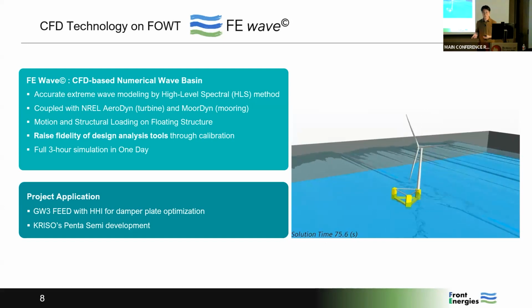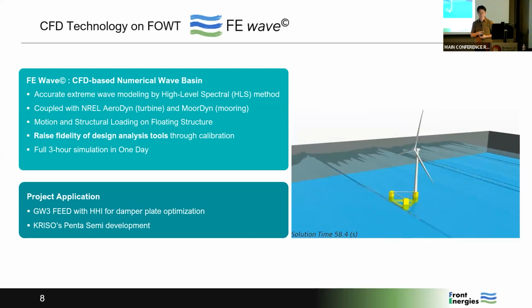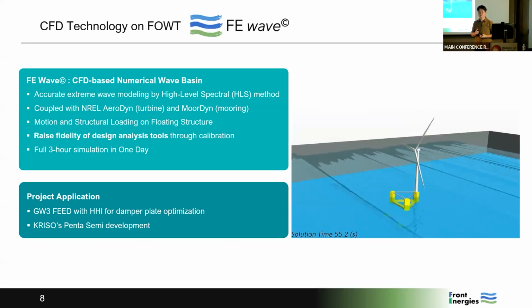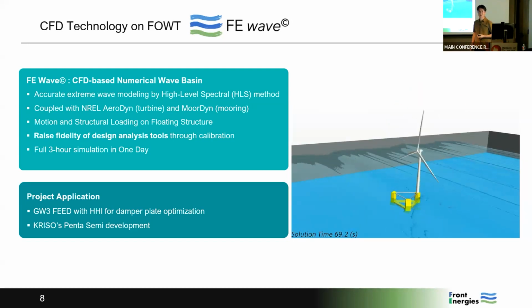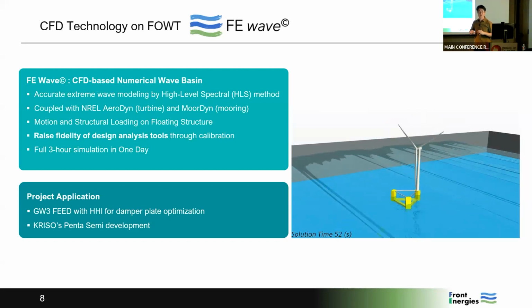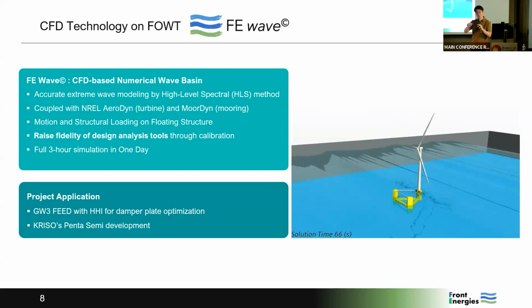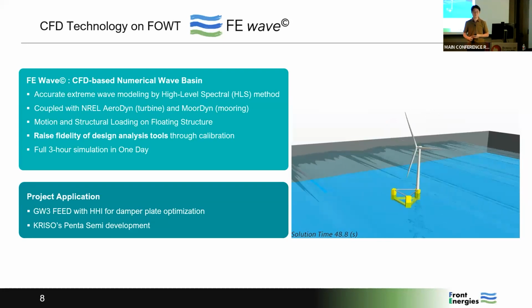This CFD technology is very important for floating offshore wind turbine design analysis, because there are so many uncertainties without model tests. Even with model tests, there are many limitations, because currently a model basin cannot exactly replicate the turbine modeling. It has different similarity rules, and there are difficulties simulating flexibility and the corresponding control system.